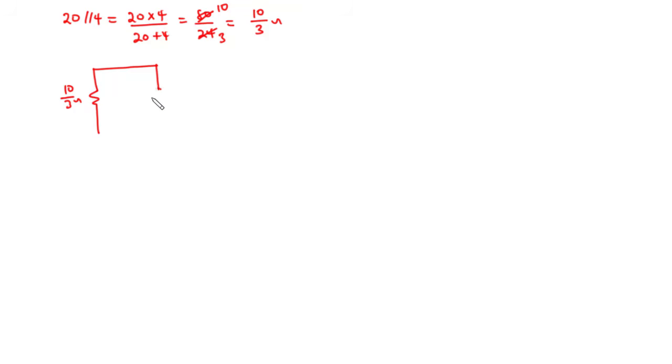We have the current source, which is 4 amperes, and then we have the dependent current source. So this is the independent, this is dependent, that is 0.1 Vx, and then we have this to be Vx. Now we have 4 amperes, 0.1 Vx combining at this node and then moving in this direction. So that is 4 plus 0.1 Vx.